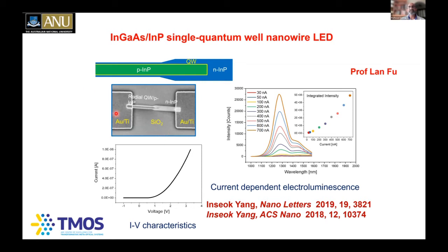By replacing these metals with indium tin oxide and aluminum zinc oxide and other transparent conducting oxides, we minimize the amount of losses we are creating, but still are able to inject current and reduce the contact resistance. That's been the major challenge.